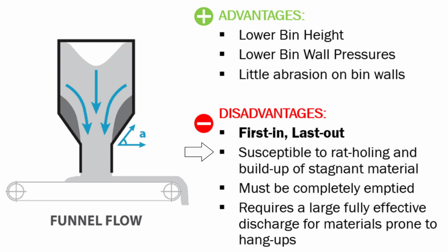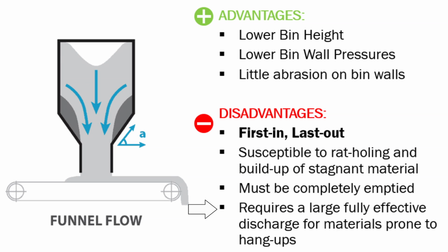holing. The second disadvantage, and this is a big one, almost literally, the geometry required for reliable flow, specifically the minimum discharge opening, can be very, very big. And sometimes the minimum discharge opening is so big, it is bigger than the bin that you're designing.